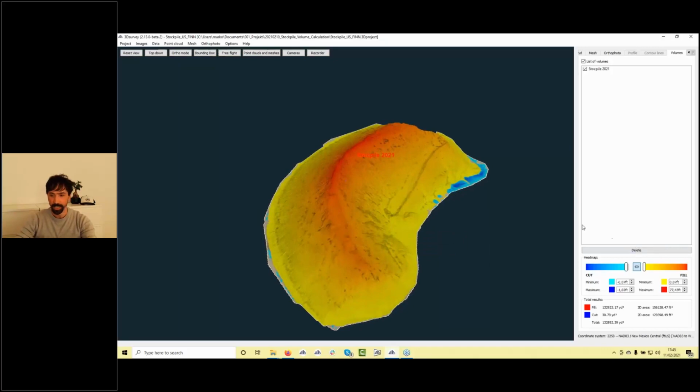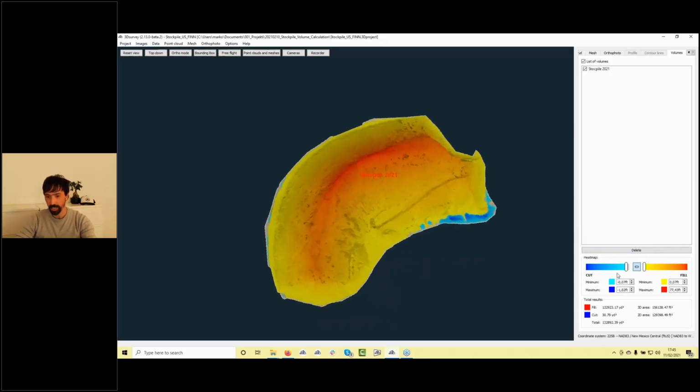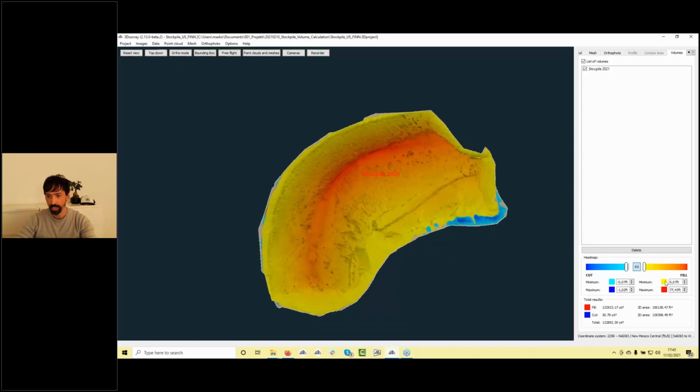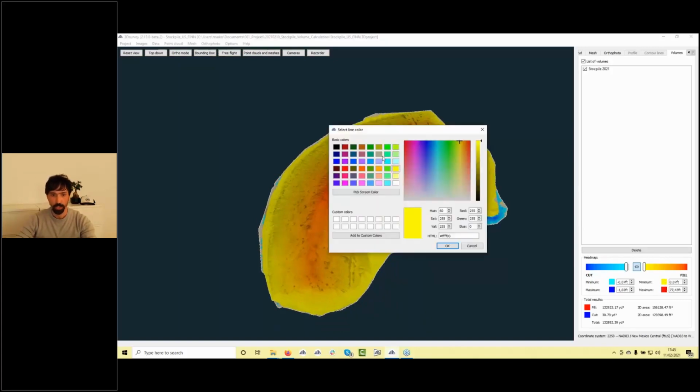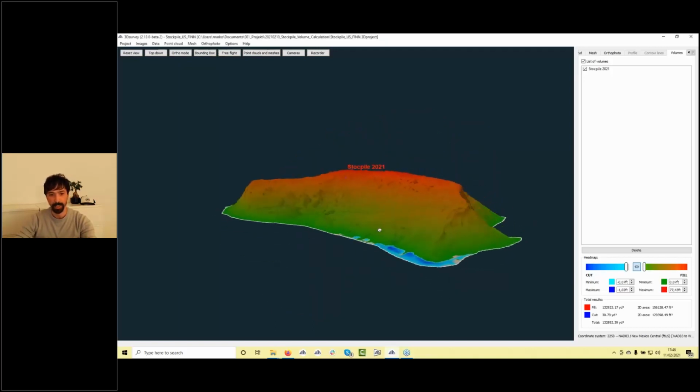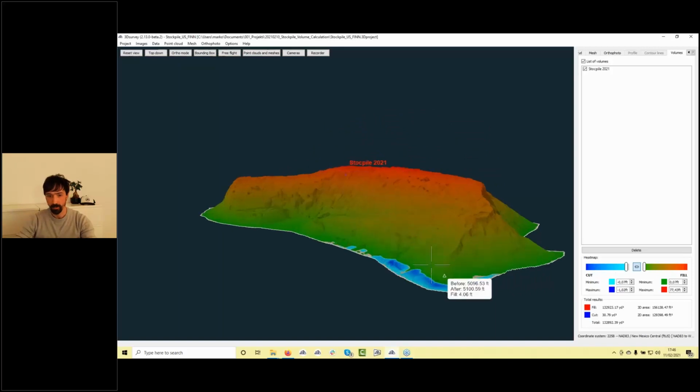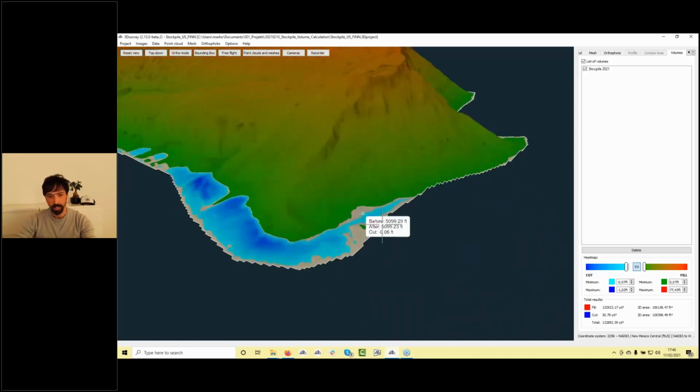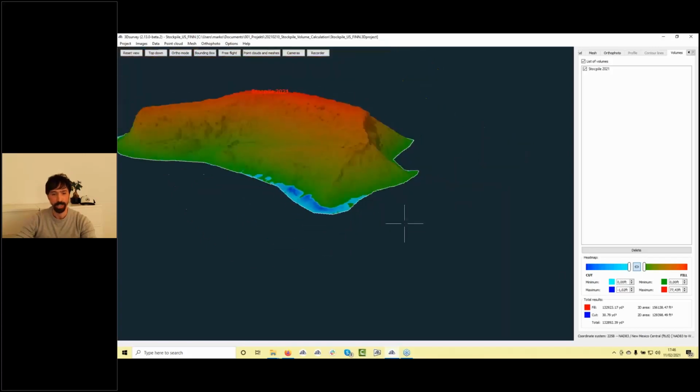Then here is an interface where you can change a few things. For example, you could change colors if you like. So let's go to green, something like that. You visualize it in a different way. Then we have some kind of buffer zones. So here where we have a realistic color, this is between minus 0.07 feet and plus 0.07 feet. So here no change was done. Actually the two surfaces cross together. We can increase this or lower it, anything like that.